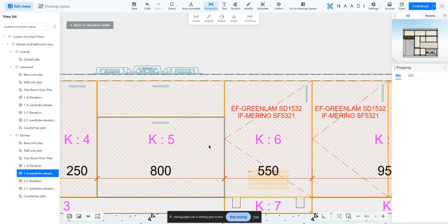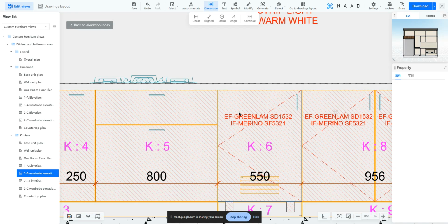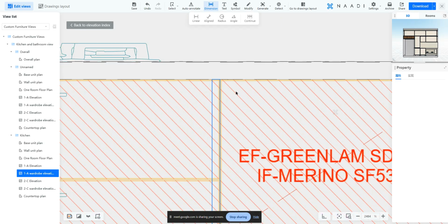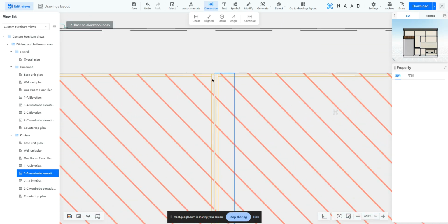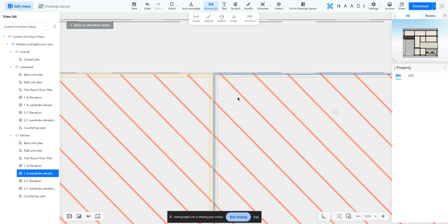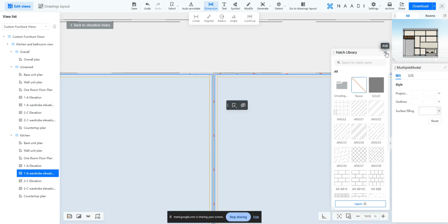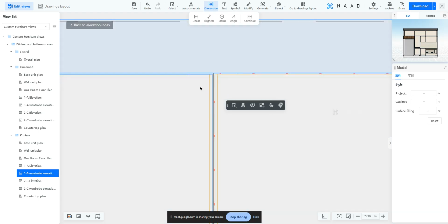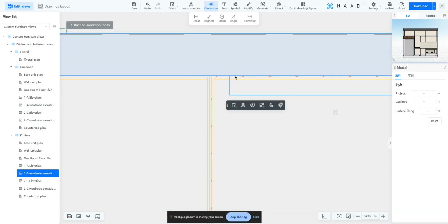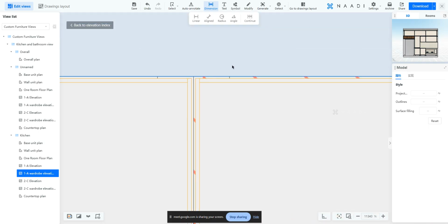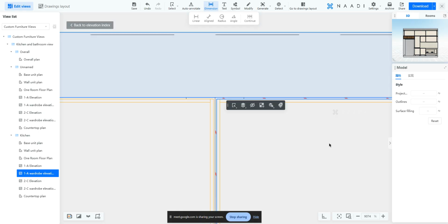Since that was mentioned, another common query which designers will come across here is, if I want to add a manual dimension, they might zoom in here and notice that there are so many dimensions. In the initial phases, designers will get confused. They might be like, there are so many dimensions here, which dimension should I select? The reason you are having multiple lines here is because that is how the cabinet model is configured in the backend.